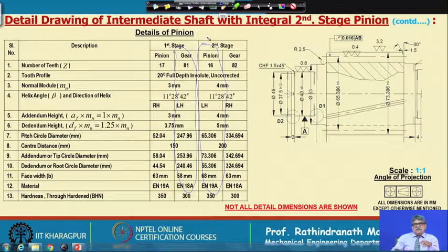This will easily, if there is some mistake or something, one can easily understand. Only this pinion dimension will do, but one can provide these two dimensions. No harm if you provide this full chart there for such a small gearbox, but this has to be provided with this drawing along with the notes on heat treatment and other requirements.